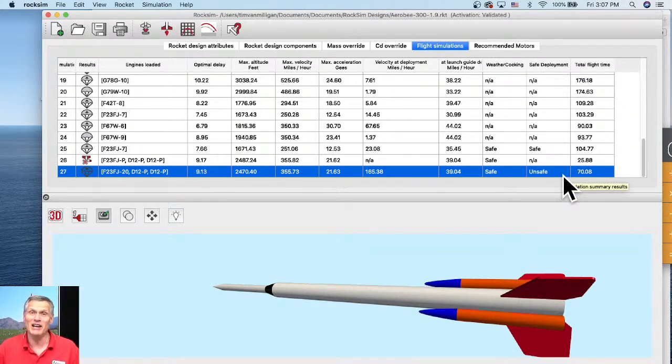But it's definitely unsafe. So it's not technically a zipper speed, but anything above 50 miles an hour. Imagine driving in your car on the interstate at 50 miles an hour and throwing out your rocket with a parachute. Will you zipper or will you shred your parachute? That's the way you would probably test it if you wanted to figure it out. That would be a simple test. Just hold your rocket outside the window, throw the parachute out, and see if it shreds the parachute or zippers the tube first. Because eventually you're going to shred the parachute, because at 50 miles an hour, if it hangs out in the wind long enough, it's probably going to rip the parachute shroud lines off.